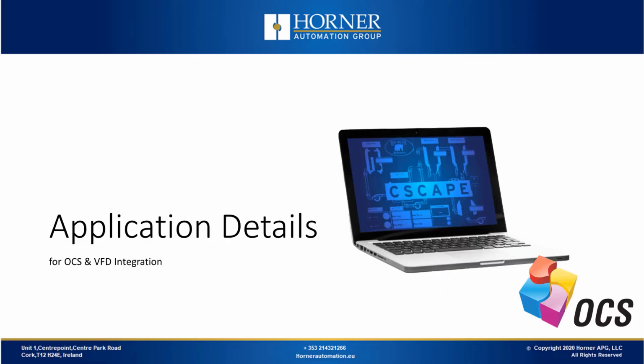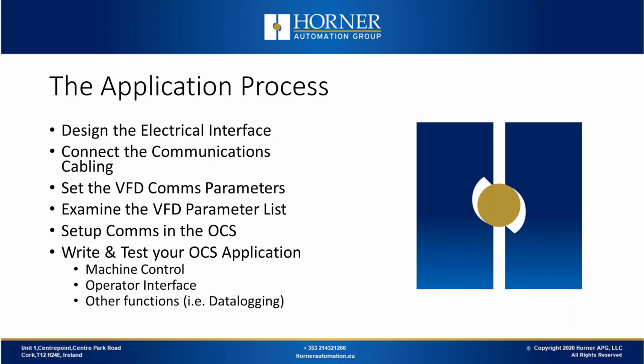Now, let's talk about how you would go about setting up these two components to talk to each other. Here's a map of the application process. These are the steps we're going to go through, and I'll demonstrate the software setup side on the back end. We start by designing the electrical interface, connecting the communications cabling. There will be some parameters that we need to set from the keypad on the VFD, and we'll need to get that user's manual out of the drive and examine the parameter list.